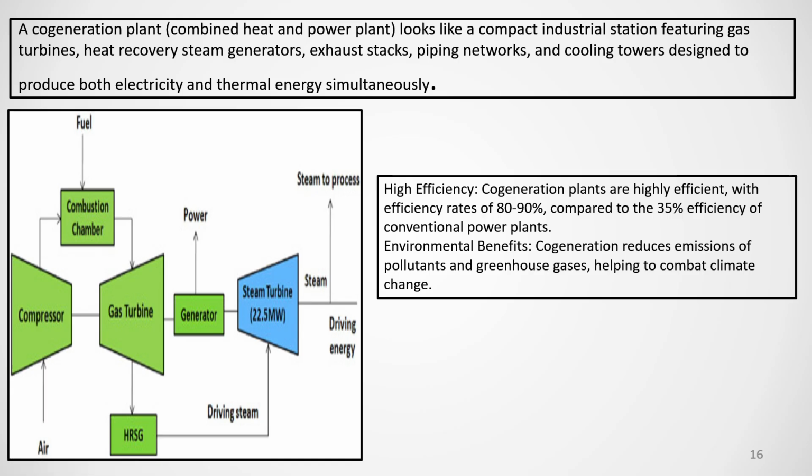That steam can be used in the turbine to generate power, or it can be utilized in a process unit. That is called the cogeneration plant. That's why the efficiency of the cogeneration plant will be 80 to 90%. Otherwise, in a normal plant, when we are not utilizing the exhaust from the turbine, the efficiency will be 35%, and the exhaust will be discharged to the atmosphere. So the efficiency will be reduced.